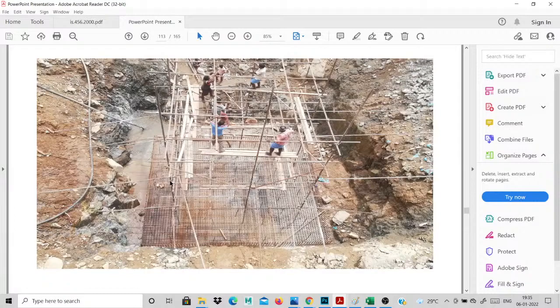Okay. This is the important point about the soil test. Once you have tested the soil, then go for any residential building or commercial building. Sometimes the client says my soil is 250. It's like an assumption, but you design for 250, while the original SBC value is 130. Automatically the structure will collapse. That is the main problem. So once the design starts, you must compulsorily check the SBC value for this area.